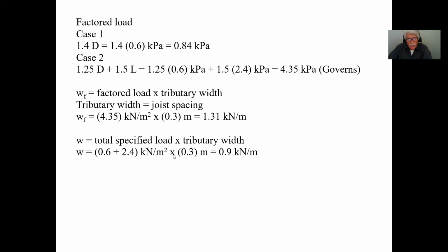And we add them both up together, and therefore this is going to be the total load that you're going to put in your joist, and you're going to limit the deflection to L over 180. If I don't say it, that's the code. The very first class, when I talked about serviceability, I told you that the CSA O86 code requires for the total load a maximum deflection of L over 180. So now I calculate my MF, of course, simply supported, and therefore I have WFL squared over 8.